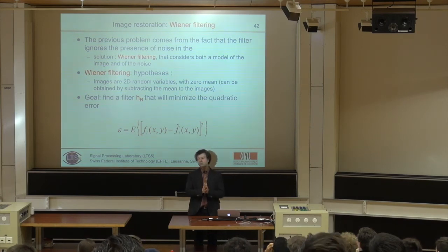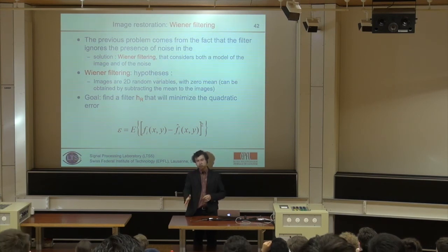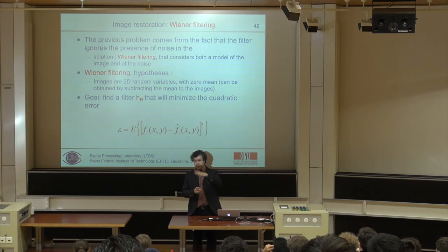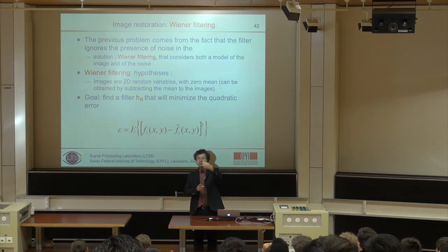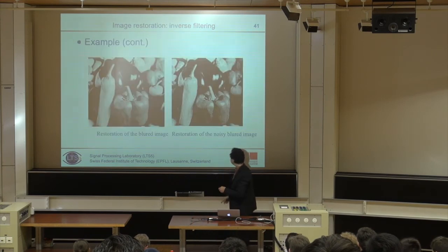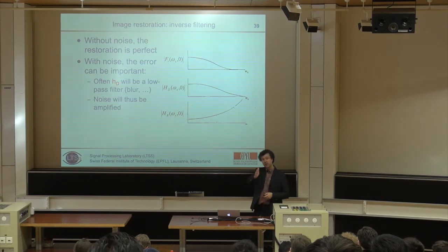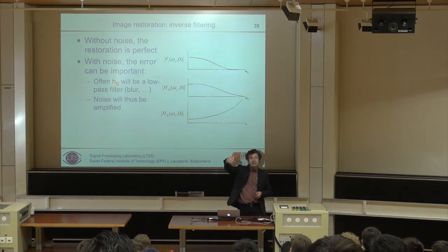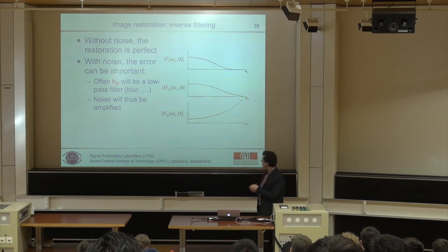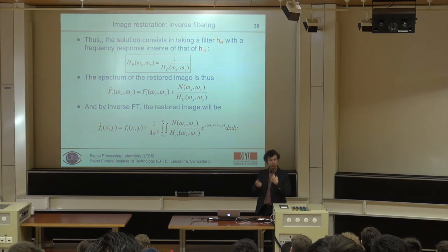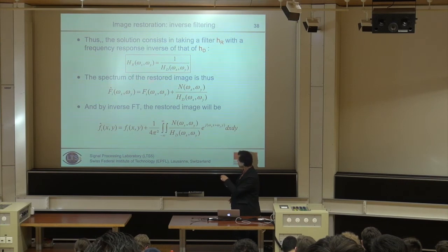You understand the inverse filter? If I have no noise, the inverse filter is, in the frequency domain, an amplification which is the inverse of the attenuation that was generated by the degradation filter. In the frequency domain, the inverse filter takes the different frequencies and multiplies them by a value which is the inverse of the degradation, such that it really reverses the effect of the degradation for each frequency. For each frequency, the restoration is the inverse of the degradation.